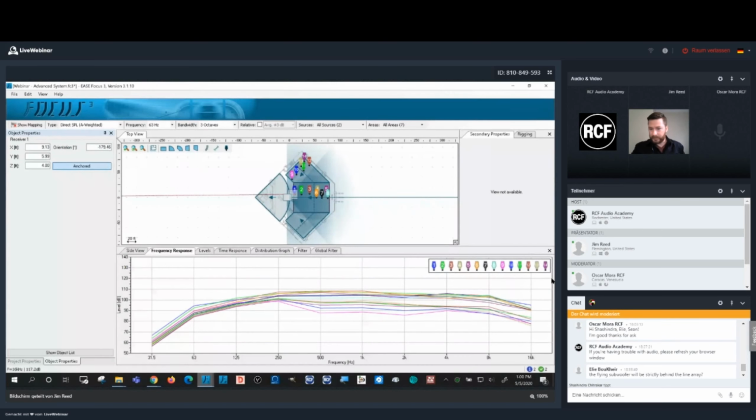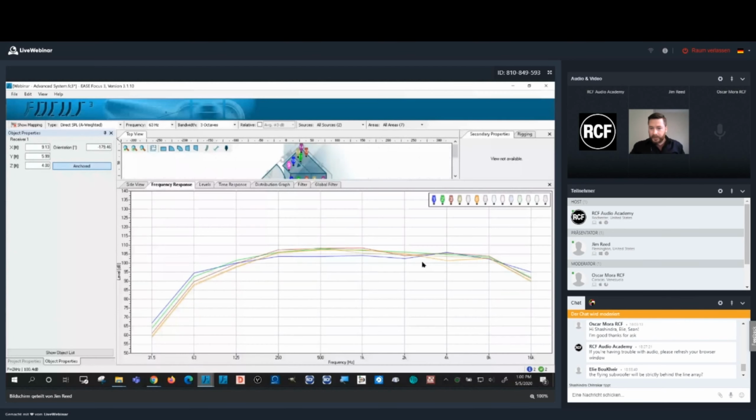Let me turn off the receivers that I don't need anymore. We're talking about this area and what should be that discrepancy. Yeah, so plus or minus 3 dB. If you hover your mouse over this area, to the top, the highest SPL point, and look at the bottom left-hand point of the screen, it's going to show SPL.